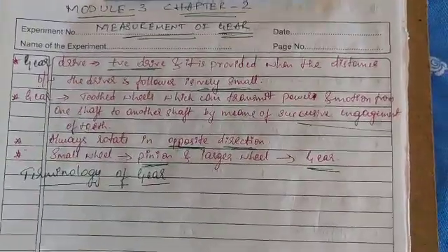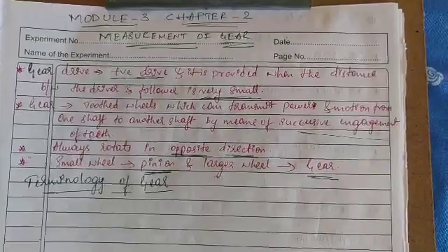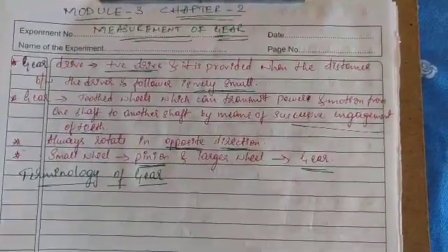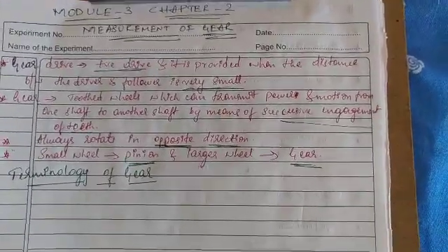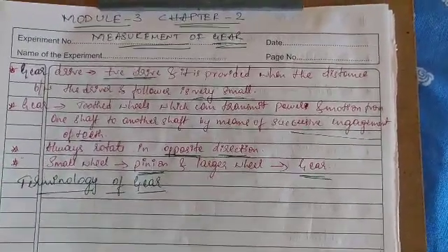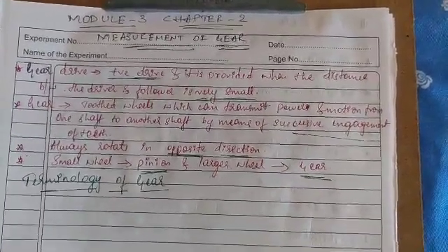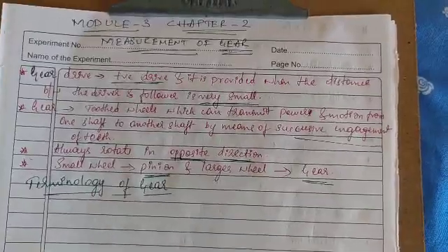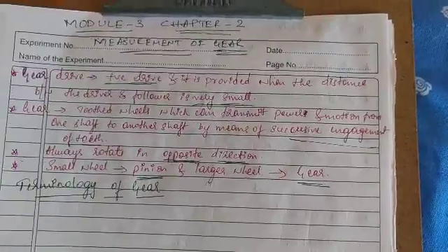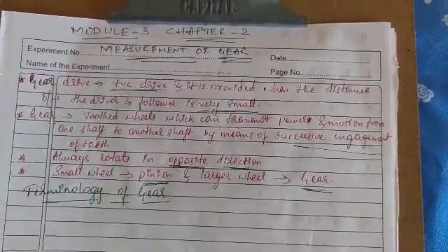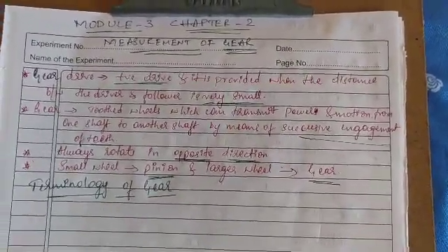The main disadvantage is that the manufacturing process of the gear is complicated, and the manufacturing cost is also high because it requires special tools or cutters for the manufacturing of the gear drive. It requires a precise alignment of shaft. That is the main disadvantage of the gear drive, and also to get a very long life of gear tooth, it requires a lubrication system for a smooth operation. This is about the disadvantages of the gear drive.